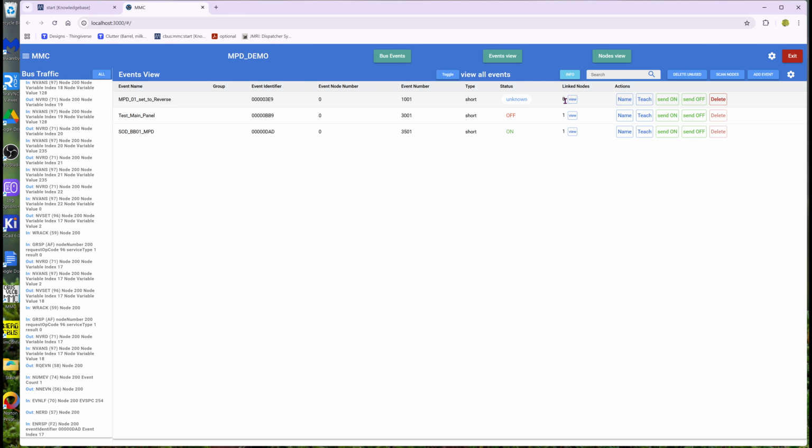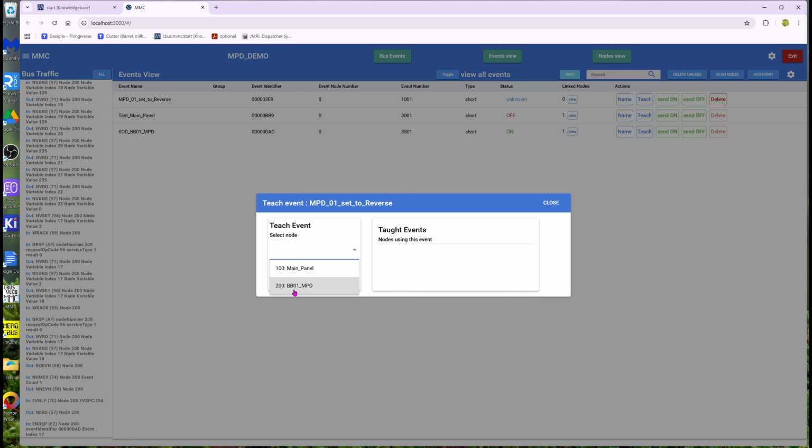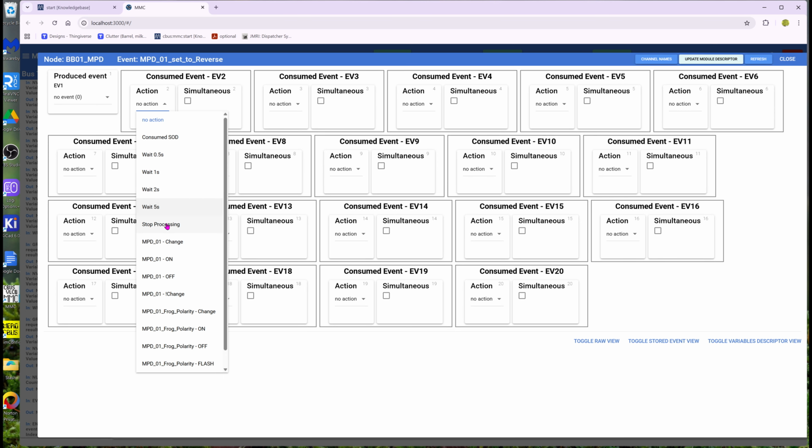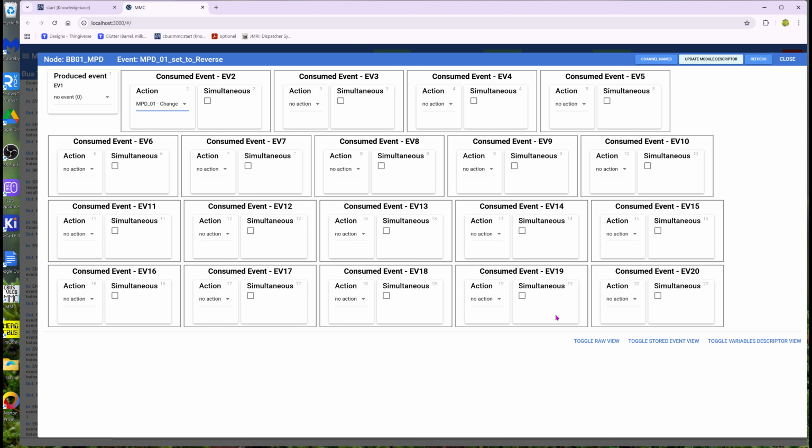Okay, how many nodes is it used on? None. What's the state of the event? Unknown. So we better teach it to a module. And we're going to teach it to this guy. So, it's a consumed event. Now, what do I want it to do? Here's where our names start to turn up again. And it's MPD01 change. I'm going to take that. And that's all I need to do to move the point.